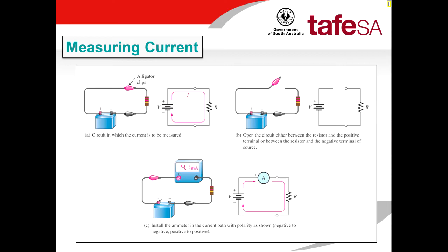The flow of power from the power source must go into the amp meter and then out of the amp meter through the resistor and back. So this is why it's much harder to take a reading, as sometimes you'll encounter circuits where you can't easily break them to take a current reading. But for our example we'll be looking at later, this will be no problem.